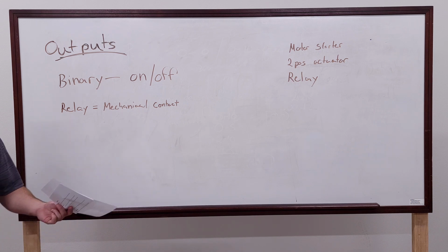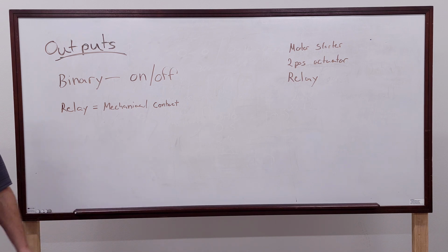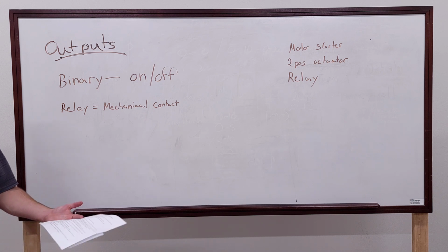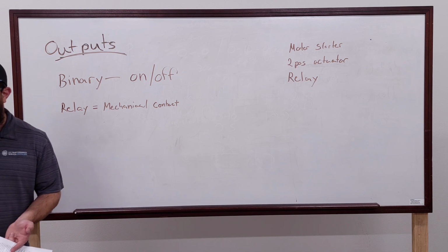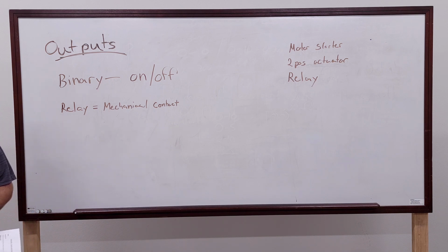Called it out, but nobody ever did, because if you've got 3 outputs on a controller and you have to add 3 more relays, that's another $100. So nobody wanted to spend the extra $100 for a fan power box to put isolation relays. Now that's pretty much all we do. We will not do a job without relays because of that problem. Are there companies out there right now that still practice non-ISOs?